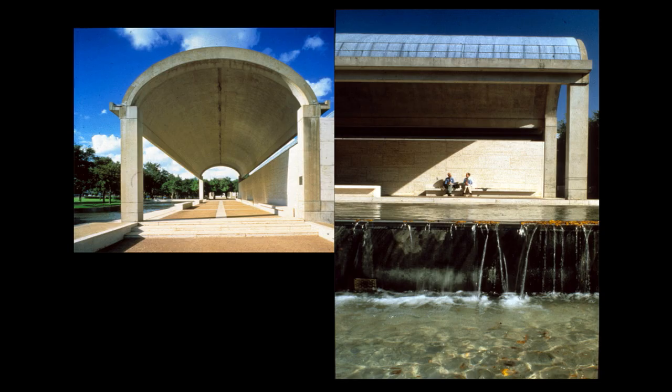What we have here instead is thin shell concrete construction, which means that it's a combination of concrete and reinforcing mesh that is poured thinly onto molds that were movable. The molds would start at one end, would support the concrete while it cured, and then would move down a little bit further and a little bit further until finally the entire structure was covered.